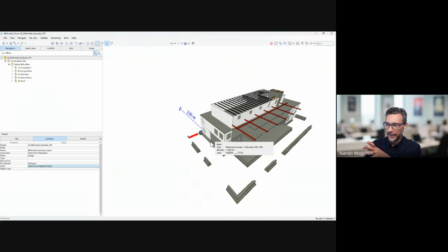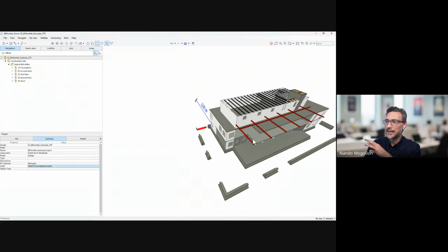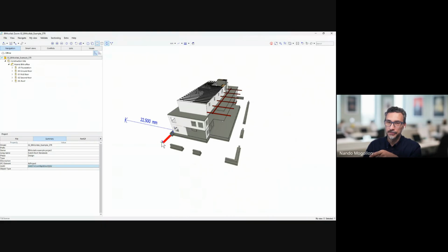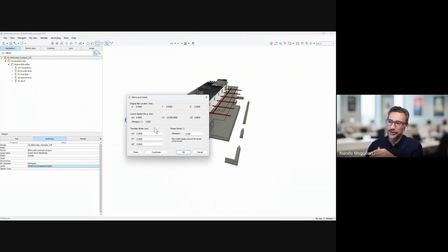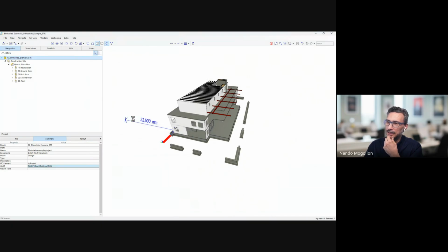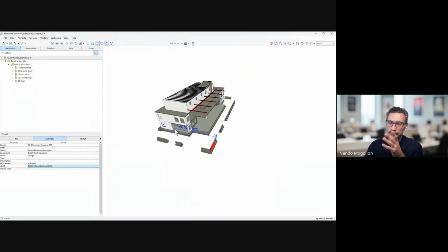If you need to rotate the model, it's better to do the rotation before you do any local transformations, because the rotation will rotate the model not from the origin, but rather from the center of the mass, if you like. I don't like it, but that's the way it is. I wish it would rotate from the origin, but it's not doing that. You can reset this. You can set these back. Delete that by clicking reset, and then the model will go back in place.